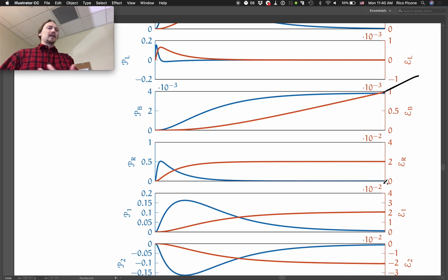Usually it goes to a trickle, and you're dissipating just tiny amounts of power because you have a very small current. The only current left in your circuit at steady state is whatever needs to flow to apply enough torque to overcome the little bit of damping torque. The damping torque is always trying to slow you down, so you always have to be opposing it with your motor.